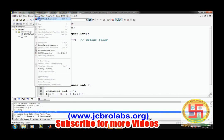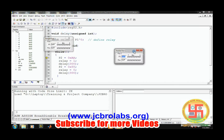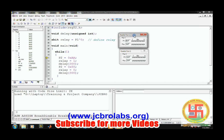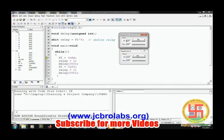Yes, so we can also debug it. Let's check whether it's working or not. So port 1 and port 2. It is very easy to write a program for interfacing a relay. The only thing is the hardware circuit diagram, which can get a little complicated sometimes. So it's 1, then it's 0, so it's working perfectly.